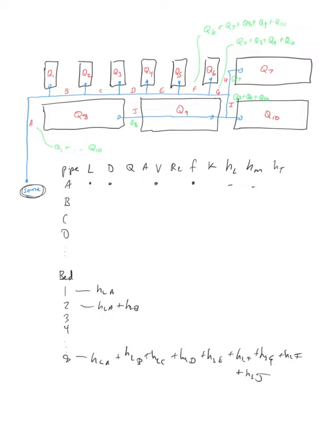Okay, so one key thing to think about here is that this is not a simulation. We're not developing a model that is going to simulate reality. We're developing a design tool in order to size these pipes, so not only size, but also develop what the schematic of the pipeline layout is going to be. That doesn't mean that when we turn on the water, these exact flow rates are what is going to come out of each outlet.